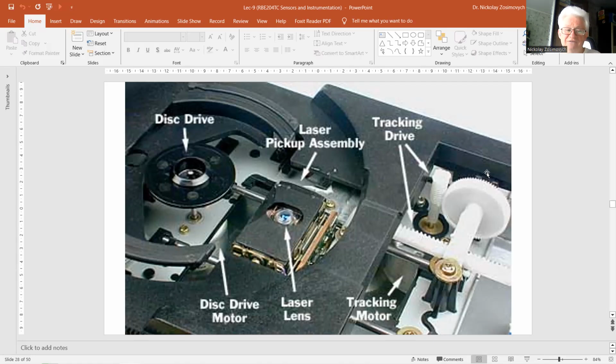This guarantees a fixed position of the beam, exactly between the tile pair or in the center of the quad. Displacement information is derived from the actuators controlling the beam position. In this way, accurate position information is acquired with a rather inaccurate optical sensor. Similar concepts are used in CD players to keep the reading path exactly on the right track of the disc.